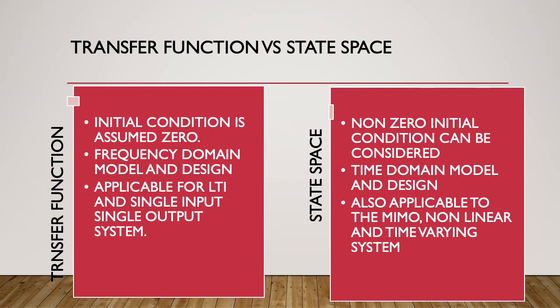However, state space analysis has a few advantages over the transfer function design. A non-zero initial condition can be considered in state space analysis, which is a time domain model and design. It is a time domain design. State space analysis is also applicable to nonlinear systems, multi-input multi-output systems, and time varying systems. So it is applicable to any kind of physical system. For example, if you have a biomedical representation, you can define a complete biomedical system in state space analysis.